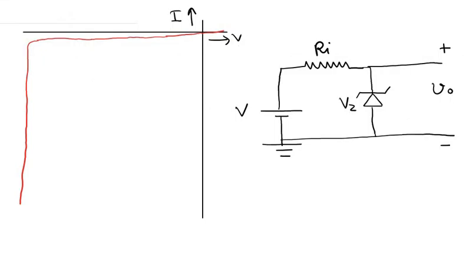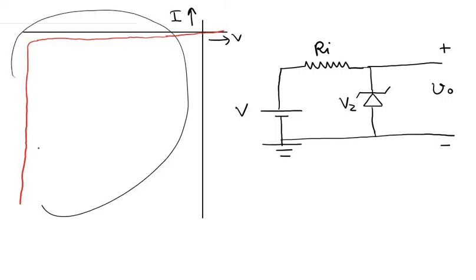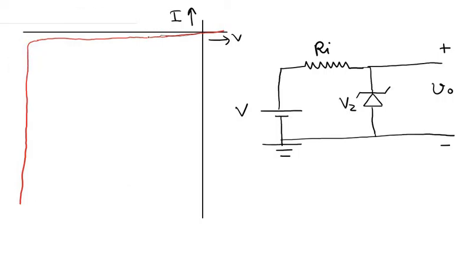Okay, so in this graph we have drawn the IV characteristics of the diode in the reverse bias situation. The current doesn't increase much with the applied bias, and then when the diode enters the breakdown regime, or the reverse bias voltage across this diode surpasses the breakdown voltage Vz, the current increases sharply with the applied reverse bias.